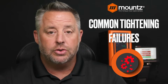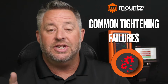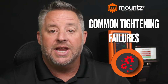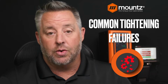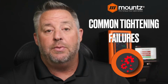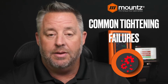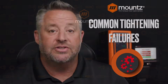If we have an over torque type of situation, that fastener may be stretched to its yield point, and any type of vibration of that is going to cause that fastener to then fail and break. And so if we can again get to a point where we're having the correct torque being applied at the correct fastening location, then we can help to minimize the actual scrap that is being developed, or at least minimize the amount of rework that would need to be done in a specific assembly process.